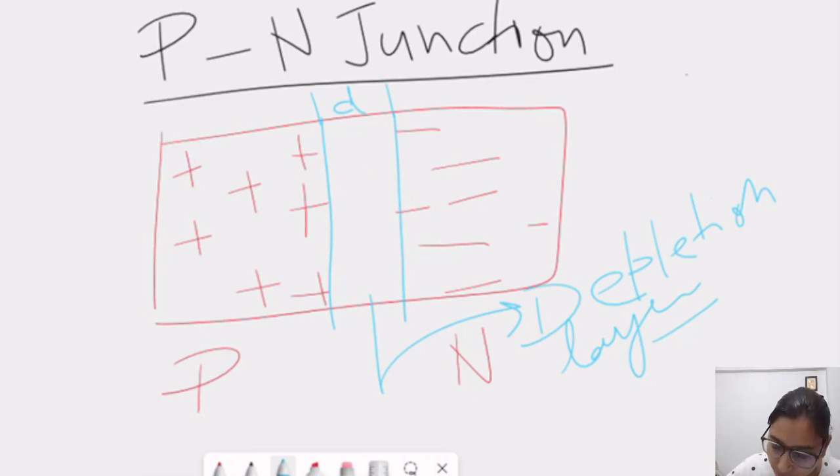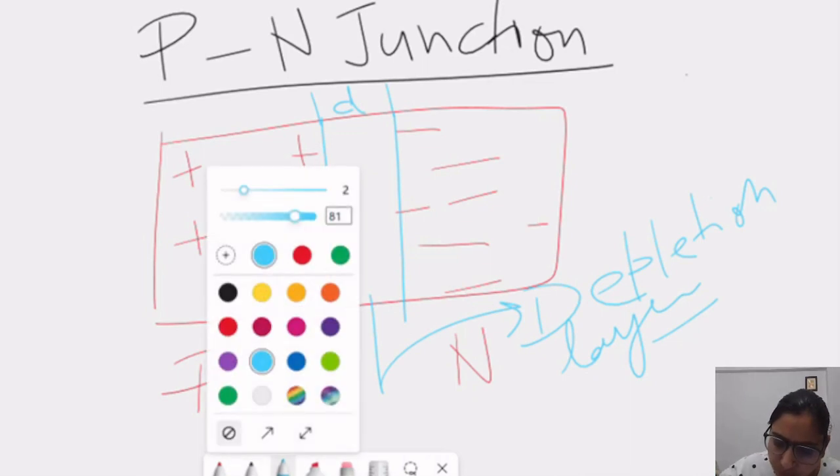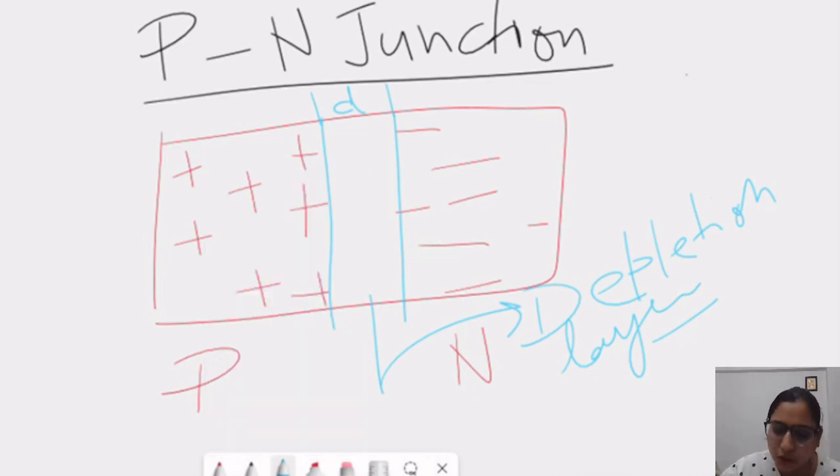Now, what will happen? See, this is not the whole picture. If this electron loses its potential, a positive polarity will be attained in this place. Why so? Because this electron recombines with the hole inside this layer. So, a positive charge will increase on this side and similarly a negative charge will increase on this side. So, positive and negative charges are there.